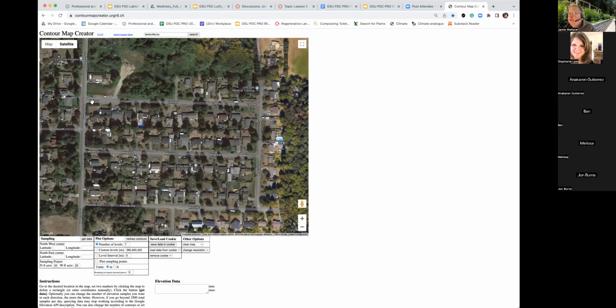So in an urban setting, we have roads that are constraints, okay? And we know in 99% of the cases that any water flowing from the other side of the road is unlikely to jump over the road and get closer to the project site, within this potential micro watershed basin.